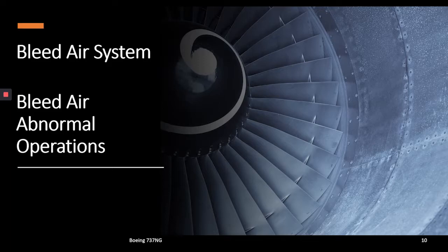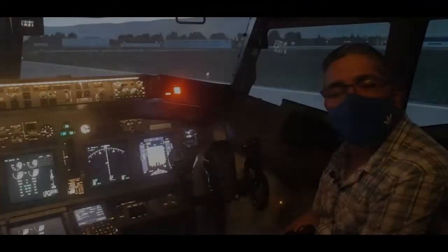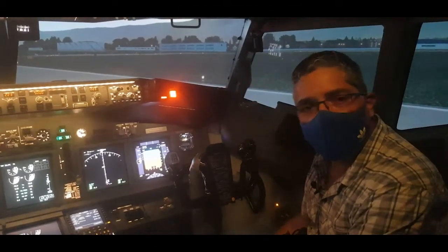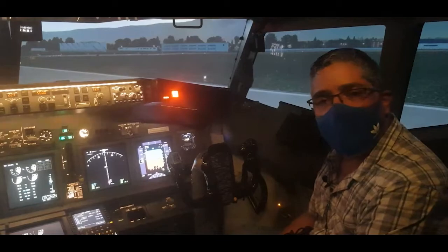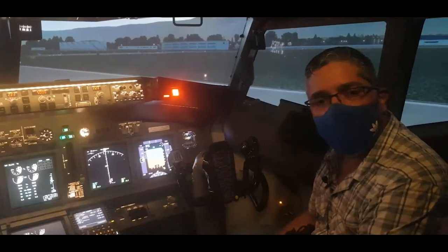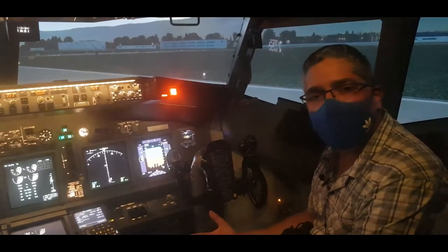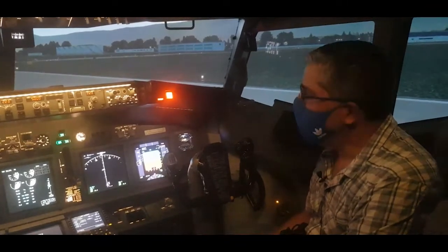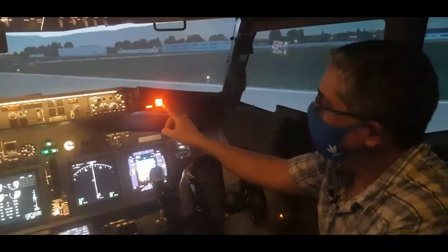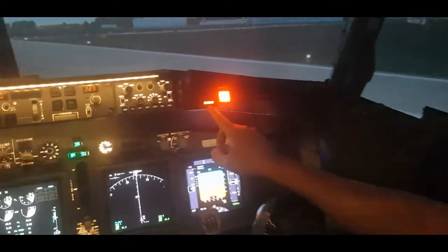Okay, now we will talk about the bleed air abnormal operations, and we have this explained in the following video. Now we will talk about some abnormals for the bleed air system. When the engine bleed air exceeds pressure or temperature, we'll see the master caution coming on with the air conditioning indication.